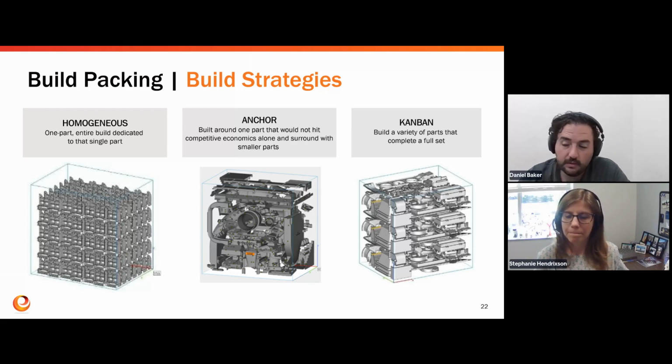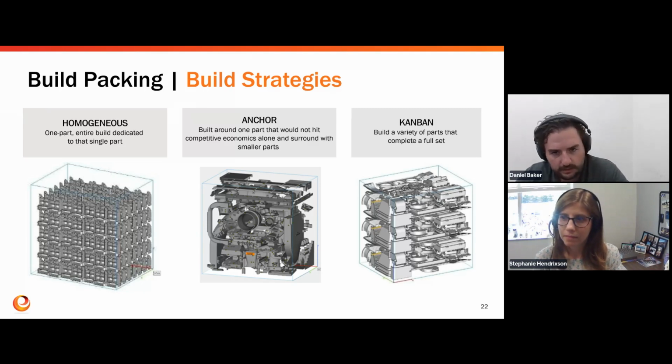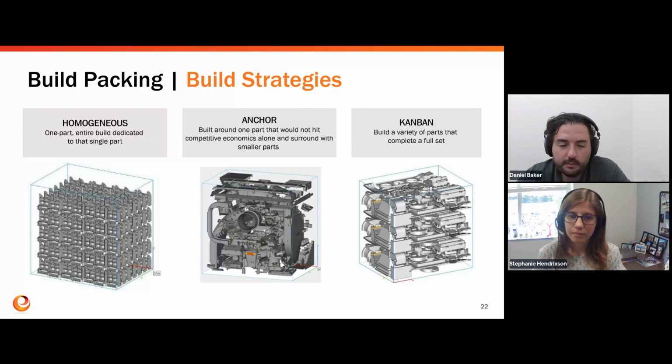So for us, it's a little easier. That's maybe another benefit to sell for HP in the Multi Jet Fusion process: you're not limited as much on the design constraints as with other technologies like FDM, where you would have to have a ton of support material, or SLA where you're adding that support material. We can typically print parts designed for injection molding, so you can have your draft angle and all of that pre-designed into the part, and you're not having to modify that post bridge production.